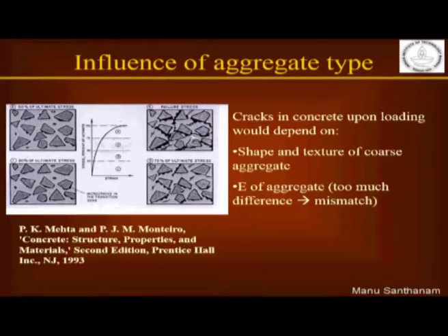Okay, now very often you use different types of specimens to determine the compressive strength. Sometimes we use cubes, sometimes we use cylinders, sometimes we use even prisms to determine compressive strength. Okay, one important characteristic that you have to understand is, depending upon the type of specimen that you choose, you may actually end up getting very different strength results. Okay, not just the load, the strength itself would appear to be different. Does that mean that the material is different? No, the material is the same.